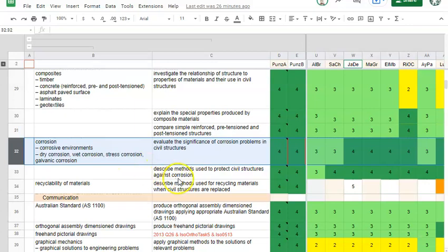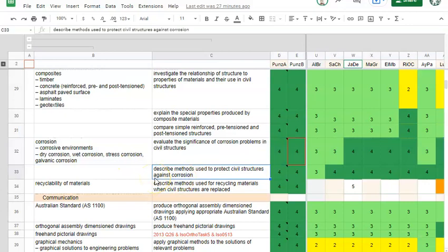Okay. Lastly, we're going to talk about how we protect from corrosion. There are three main ways. First, protective layers, right? Everything from hot and cold dip galvanizing, chrome plating, painting, nickel plating, all of those are just protective layers. We can use ICP, impressed current protection, where we add electricity to a structure so that the electrons that are lost through the reduction process are replaced. Or on boats, what do we use? Sacrificial anodes, right? Blocks of metal that we attach to the boat, and they rust instead of the boat.